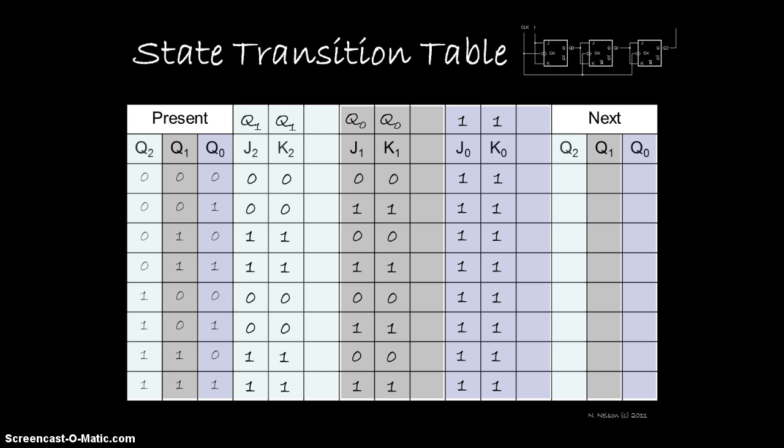The first pair of JK inputs are both low. This is the hold state. Mark an H in the transition column. The next row is the same. In the third row, J and K are both high, so mark a T for toggle. Continue this for each of the JK pairs in the rest of the column. Repeat this process for the remaining flip-flops.